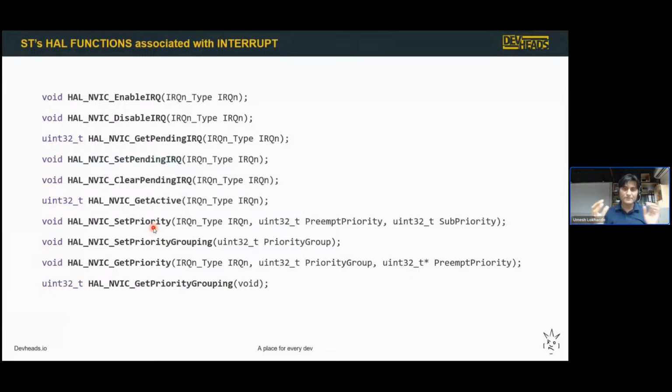So you have multiple interrupts, and you can assign the priority to a group of interrupts. That's very interesting because you can categorize them, create different groups, classify them, and then execute. That helps you write a better algorithm when dealing with very complex code execution.